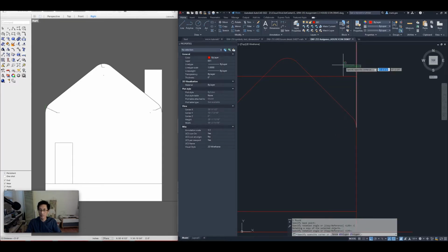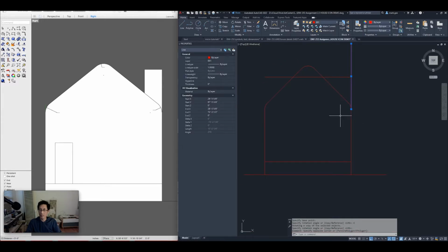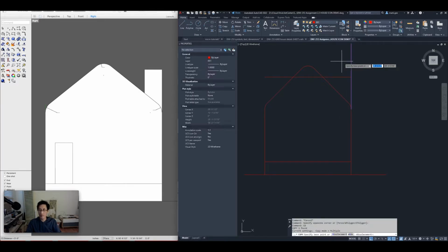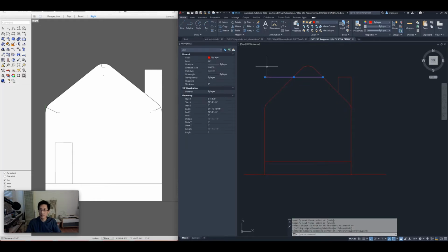So that just created a new line by copying this one around that point. The other face of the chimney, the interior face here, is 3 feet over from here. So we just copy this over 3 feet, 36 inches, enter. And let's just trim everything that we don't need now, TR. Go across there, don't need that, don't need that, and then I can just delete that.